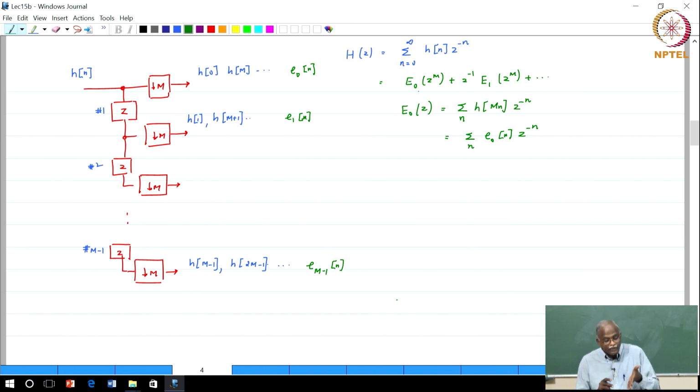So, actually what we would be doing was to split the filter into polyphase components and then apply them in the branches. But actually the structure itself has so much symmetry in it that if you feed the impulse response, the structure itself gives you the polyphase components. Again, it is just an observation of what the underlying operation of the structure is, and it is helpful for us to think of what exactly is happening when you have either a chain of delays or a chain of advance operators followed by downsampling or upsampling. The multiplexing operation, demultiplexing operation, just a way of reinforcing what we have been discussing.